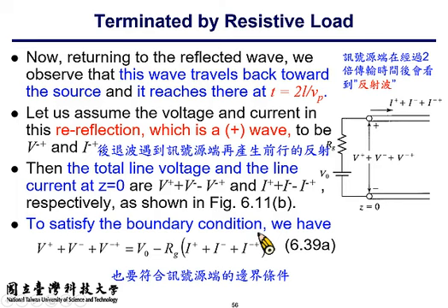Well, it's simple. You just write up the boundary condition again. That is, the total voltage over the total current should be the same ratio of RG. And considering that at the left end, you have another voltage jump at the battery, V sub 0. So the Kirchhoff KVL equation at this place, at this instant, should be written as equation 6.39a. Right? So that's a KVL equation.